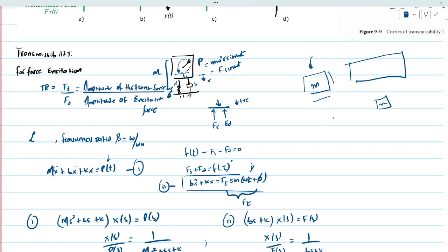We're just representing this mass as a point source, and we are doing all the calculation based on that. But in reality, you have bodies which are three-dimensional, so mass is distributed all along the body. So you cannot use this point source analogy to solve the dynamic behavior of those systems. So we'll look into continuous vibration systems.